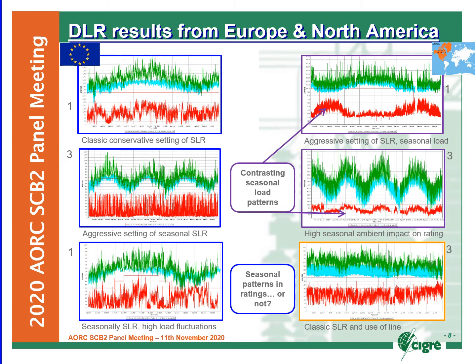Another interesting observation is that in some systems, the wind cooling effect has a huge impact on releasing extra capacity. The top left and bottom right graphs show best this effect. The blue line considers only ambient air cooling without any wind cooling, while the green curve shows the capacity by considering wind cooling. What is interesting here is that the top left graph is in a relatively cool European location, while the bottom right is in a tropical climate.